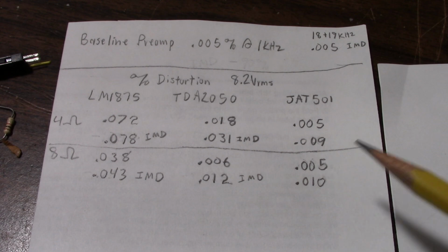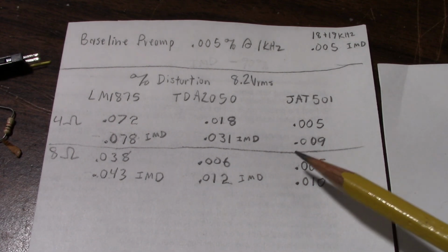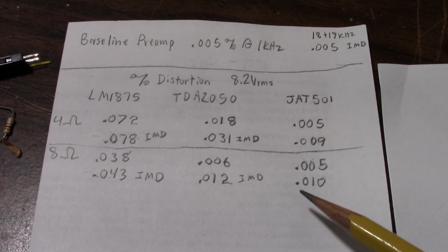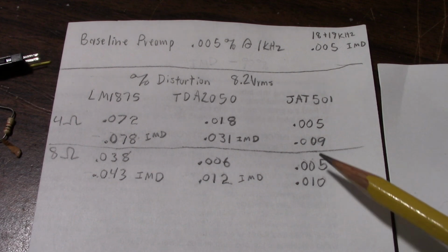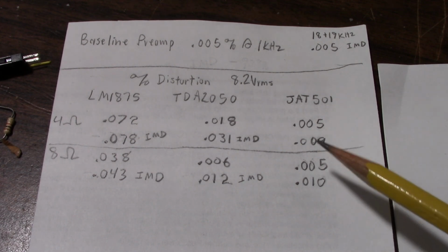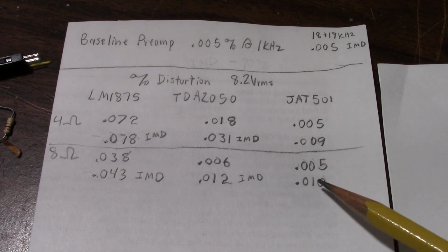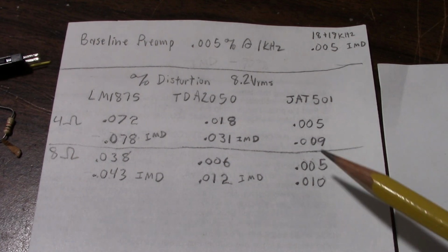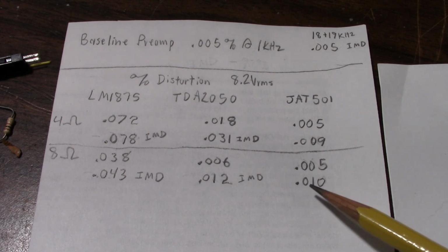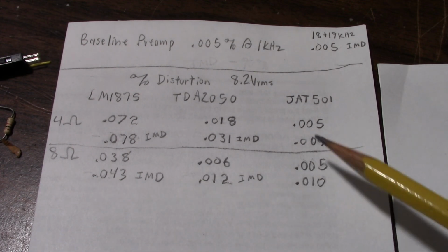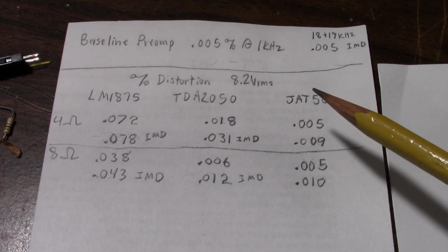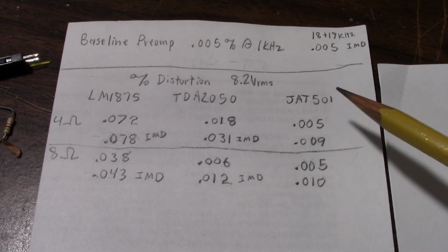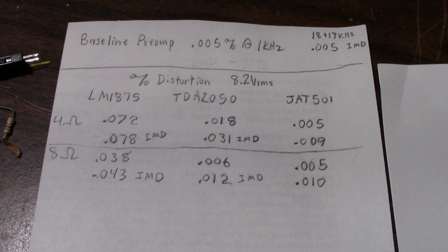The intermodulation test, it's 0.009, but what's interesting with 8 ohms, it was slightly higher. I mean, it's one click higher. It's so close to the baseline that I can't put much faith in that measurement. And because it's so close, that's probably why it's just the error of measurement. But yeah, really impressed with this project amplifier. It's stable. It just doesn't have any issues with it. Low distortion. I'm just so glad and thankful the amplifier turned out as good as it did.